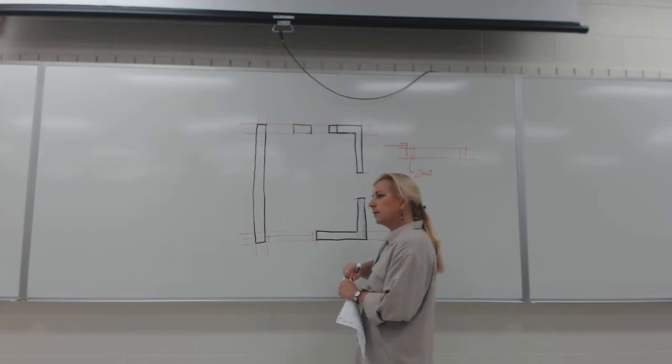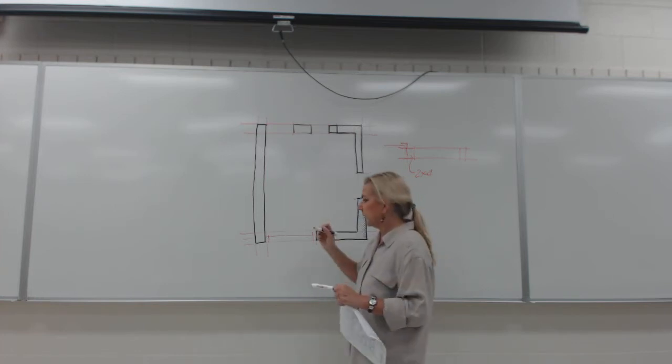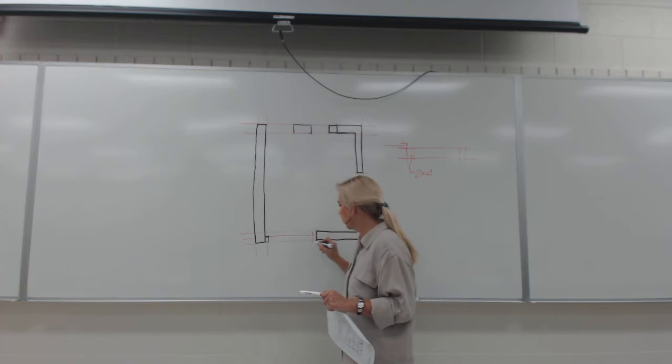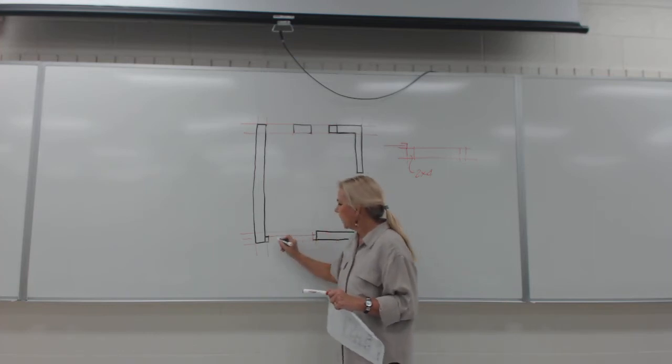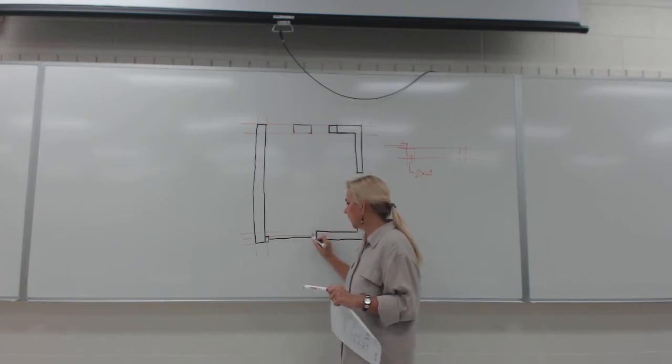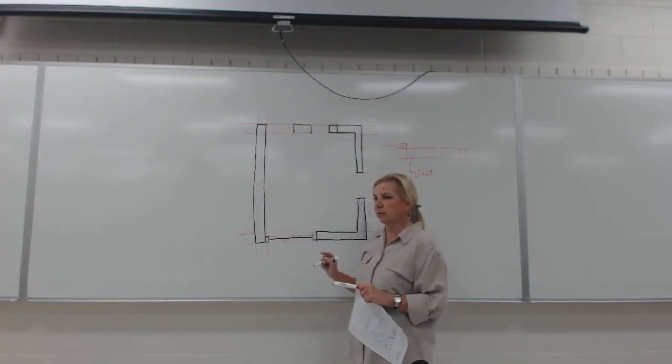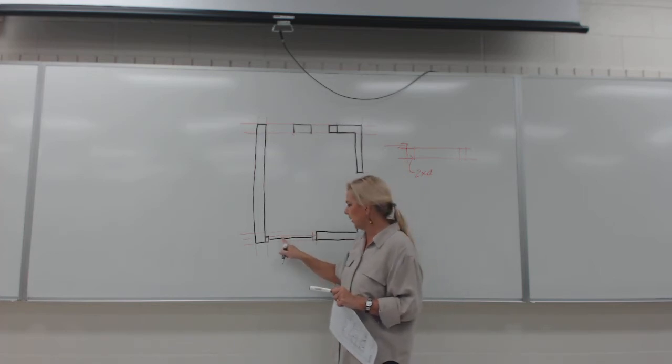So then the medium weight would be the frame, because we are cutting through the frame and we would see it. You could draw it almost as dark as walls. We're cutting them. And then one dark line for the glass, and you're done. Now, this particular window, however, if you look at my drawing, don't copy my drawing, do what I'm doing here.